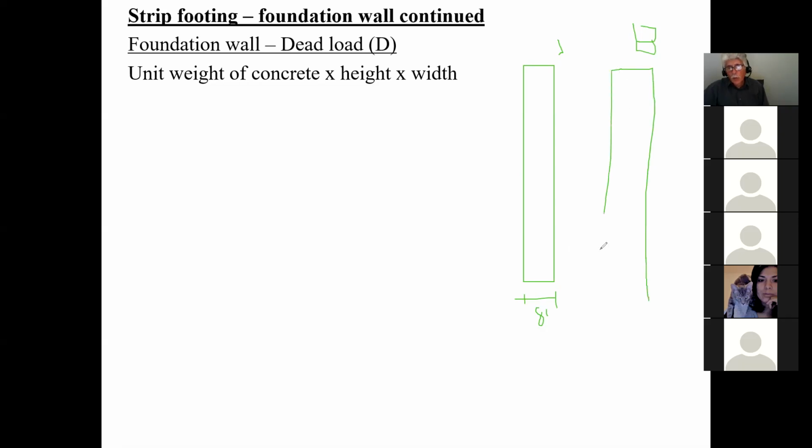Why are they thicker? So that you can create a seat for the masonry. So if it's masonry, it's 10, and when it's no masonry, it's 8 minimum. So that's how you keep it in mind. If you want to make them 12, make them 12. It's up to you. But 8 and 10 are the typical sizes for residential foundation walls.